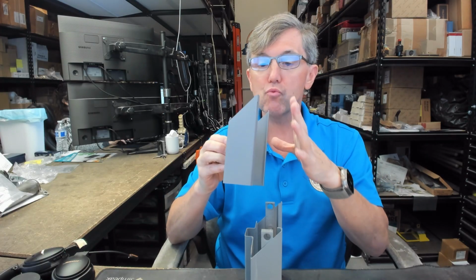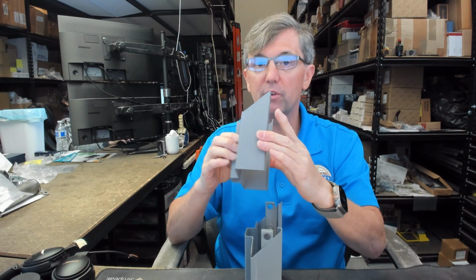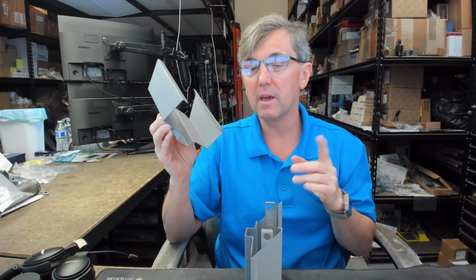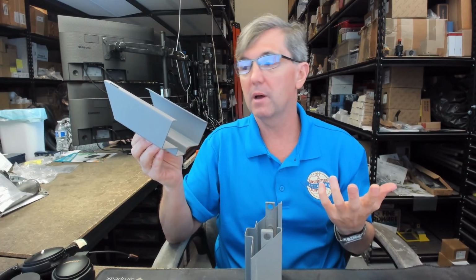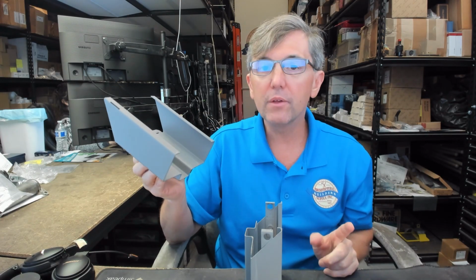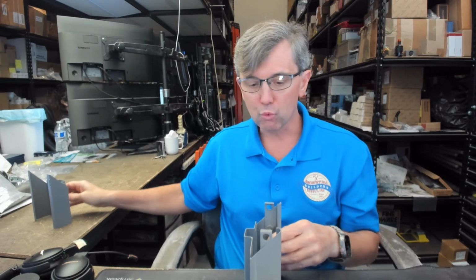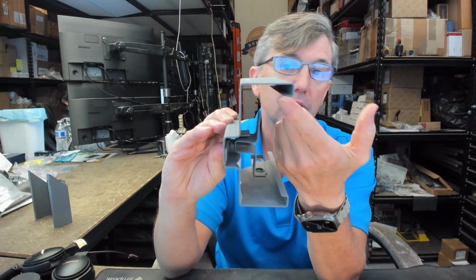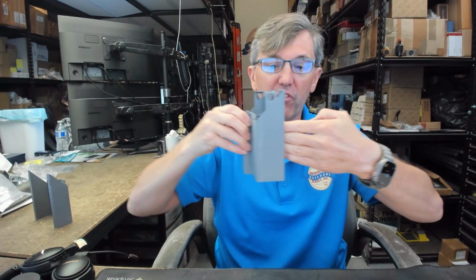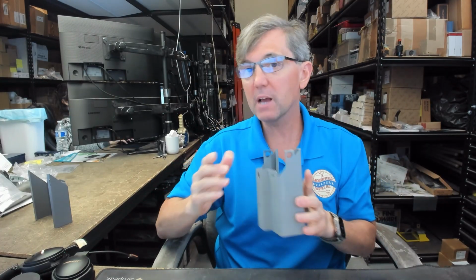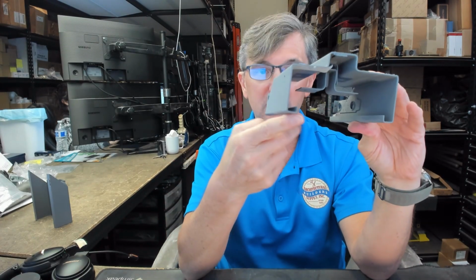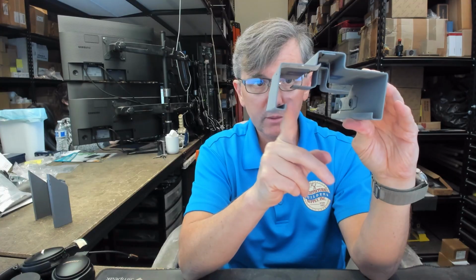So you don't ever want to sell masonry frames to someone who's going to install them in a partition or a drywall type opening, because they're going to call you and tell you that the back of the frame ripped the paper of the drywall off. So you really, really want and need the back bend return, because that will prevent that from tearing back. So back bend returns are inherent in the design of drywall frames.